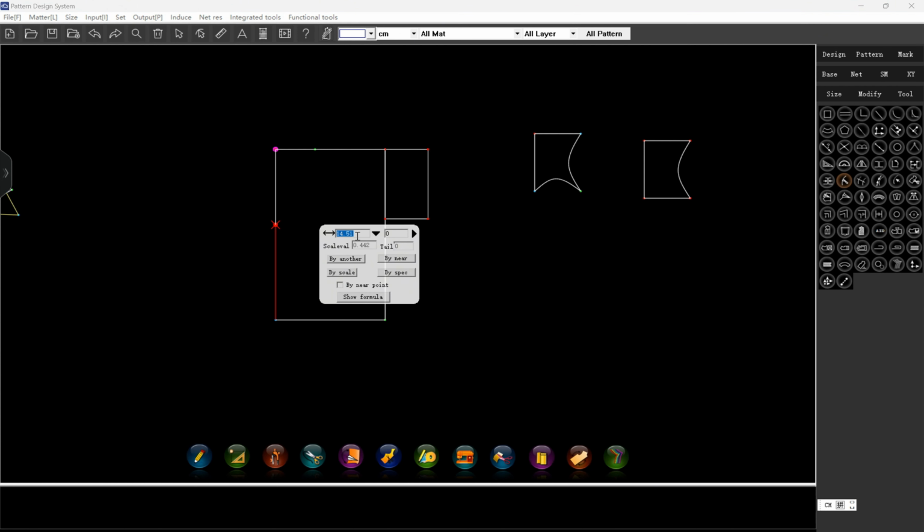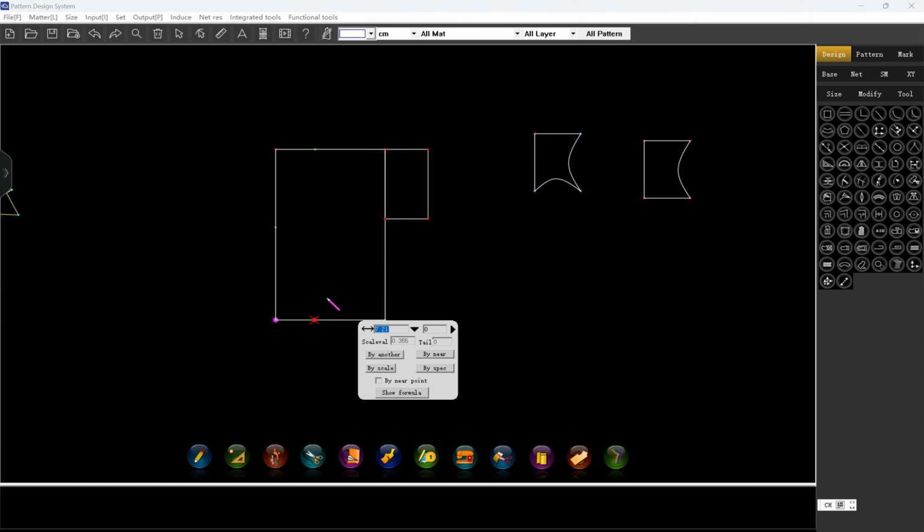Here you can determine the cutting position. When you finish, right click. Now you can see it's two lines, right? Or you can choose a point here in advance and then choose the tool split line and click the left button on the line. Now the line is divided too.